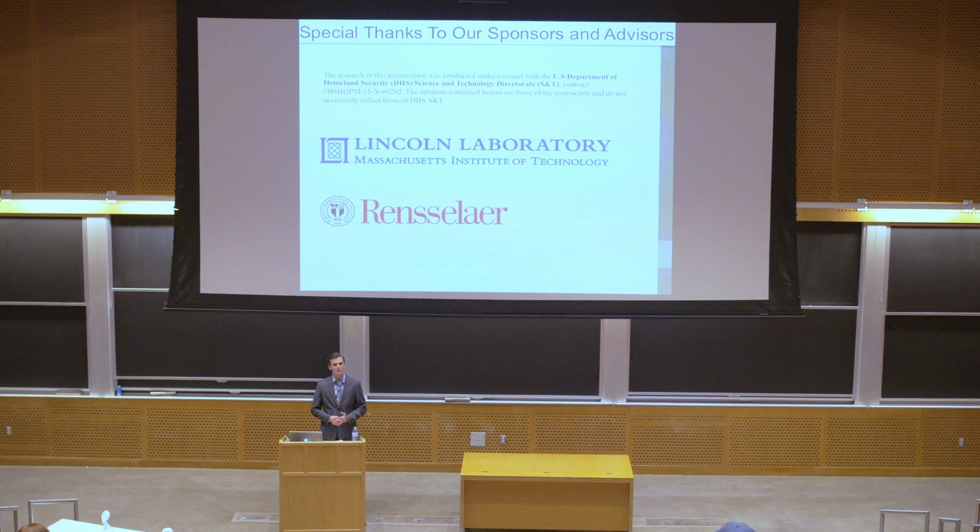How is the indoor climate with this drone? Great. So the cameras that I briefly mentioned, which was time limited, the stereoscopic imaging that we use once we get indoors is pretty awesome, actually. I don't know if many people have an understanding, but it works similar to your eyes. You have two cameras and a known distance between them, and you get a depth field of the surrounding area.